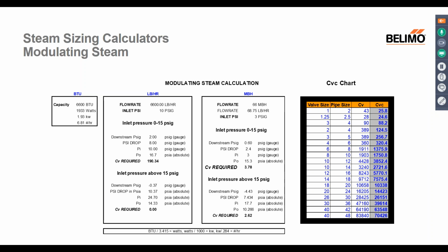We have a system, and I believe it's the only one available, that actually selects the entire valve for you. What I always liked about this, it had this little BTU calculator over here. It does corrected CV. It does the pipe factors. If you're coming down more than 2 pipe sizes, it's recommended to calculate a corrected CV because it's going to reduce. At a specific pressure drop, which you want to maintain through an orifice, you can only get so much steam. So that's why this is important, that after you did your sizing and you're going from, say, 6-inch pipe to 4-inch, you might just want to check.